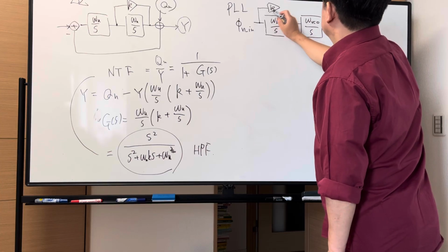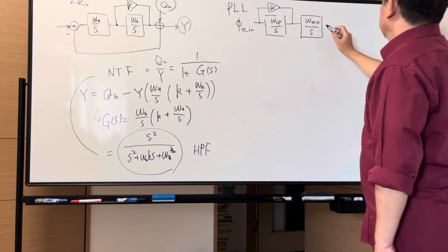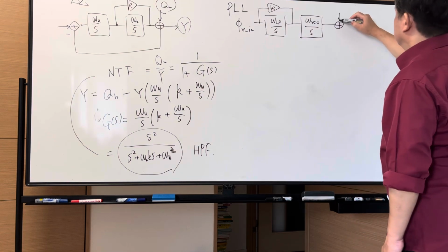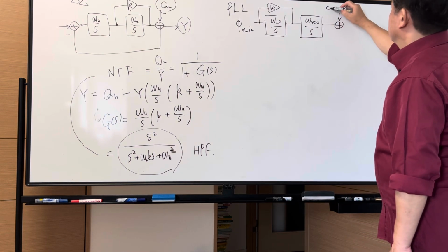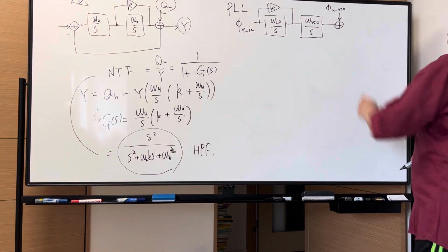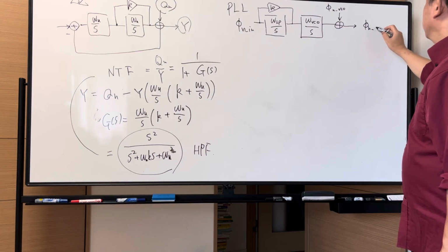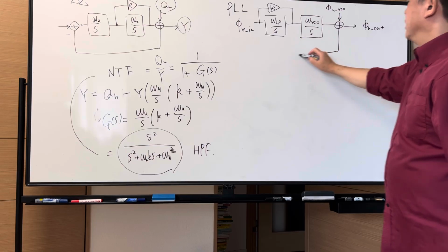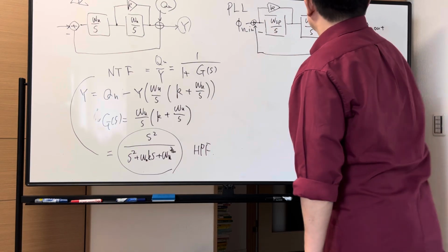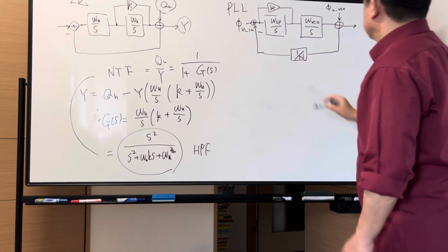Likewise, there's a feed forward path for stability, making a zero, and in this case, the VCO phase noise is applied after the VCO block, and it makes the output phase noise. This is fed back to the input negatively, and there's a divider 1 over n, where n is an integer.